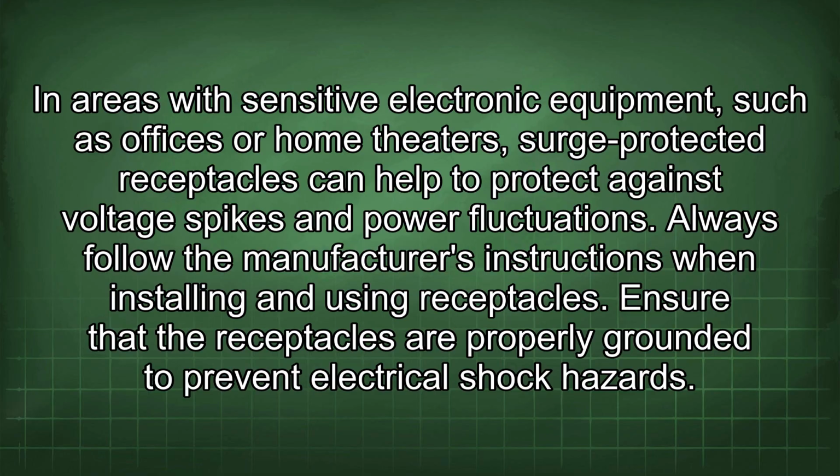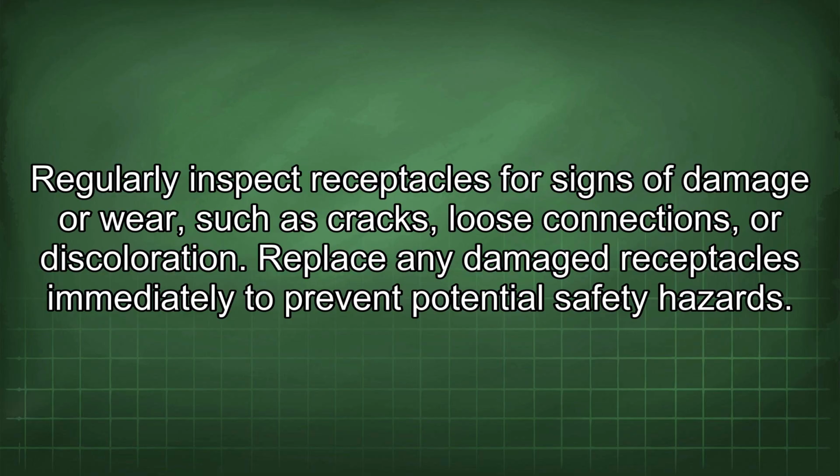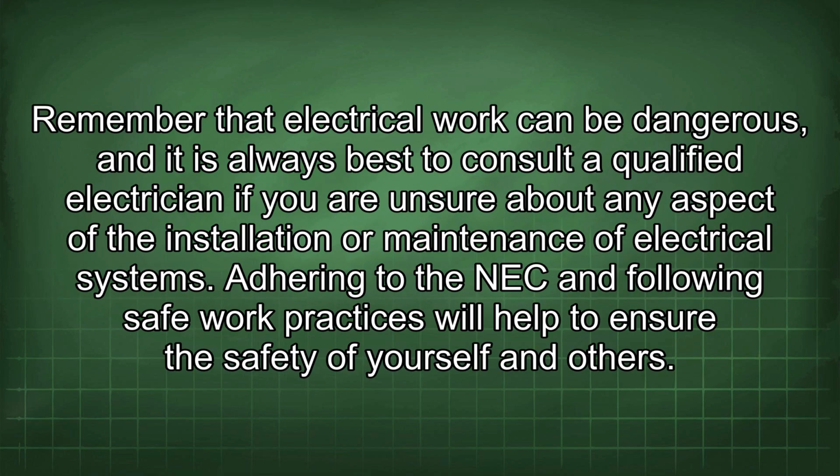Ensure that the receptacles are properly grounded to prevent electrical shock hazards. Regularly inspect receptacles for signs of damage or wear, such as cracks, loose connections, or discoloration. Replace any damaged receptacles immediately to prevent potential safety hazards. Remember that electrical work can be dangerous, and it is always best to consult a qualified electrician if you are unsure about any aspect of the installation or maintenance of electrical systems. Adhering to the NEC and following safe work practices will help to ensure the safety of yourself and others.